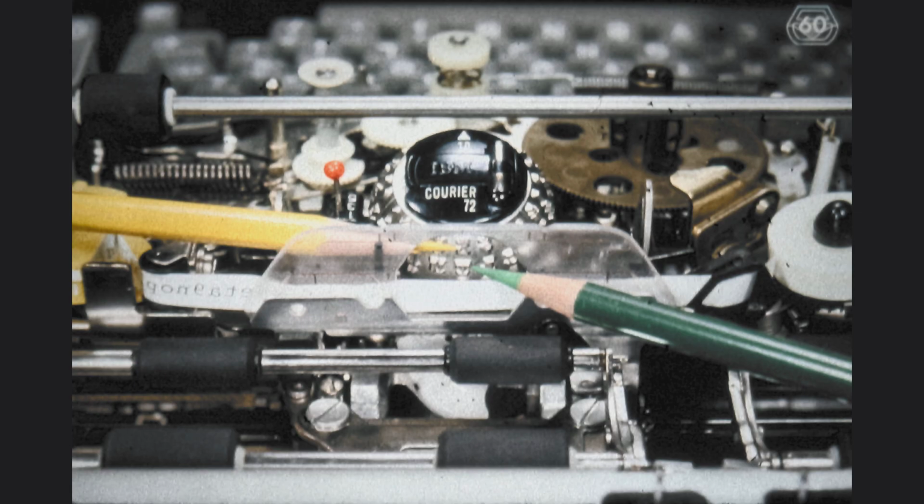If, however, we wanted to print a T, indicated by the green pencil, we would need to tilt the element by one tilt increment. We would have to rotate the element in the vertical plane by an angle that allows us to print a T, the character in the second band, instead of a Z, the character in the first band. The character situated below T is the degree mark. In order to print it, we would need a rotation in the vertical plane of 2 tilt increments. Below the degree mark there is a J. In order to print the J, we would need a rotation in the vertical plane of 3 tilt increments. Therefore, we say that J is a tilt 3 character, T is a tilt 1 character, the degree mark is a tilt 2 character, and Z is a tilt 0 character.